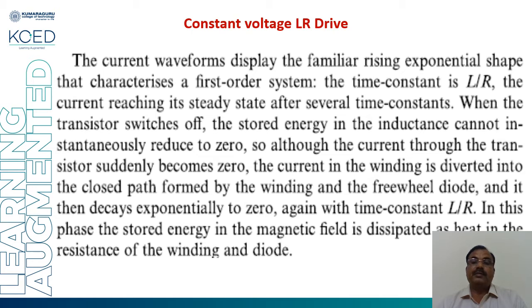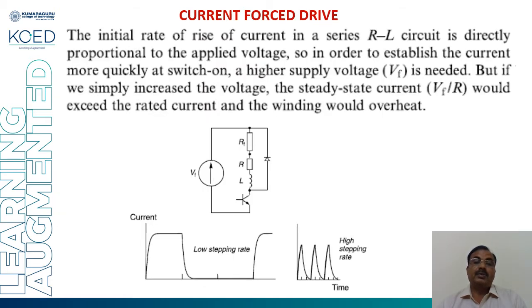In these current waveforms, we can see the things we have discussed earlier. We provide immediate pulses, so the current doesn't have the required time to decay to the zero value. So the problem with this drive is that for high stepping rates there is no time for decay.